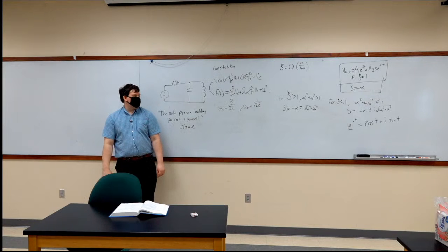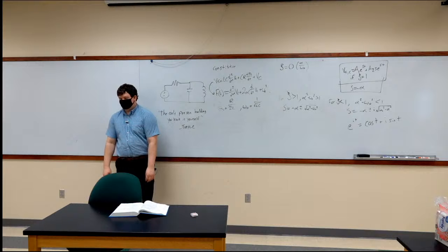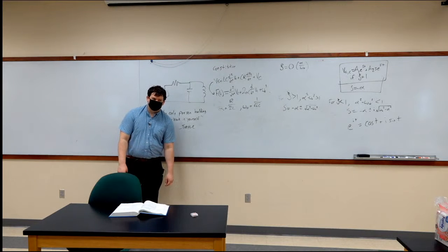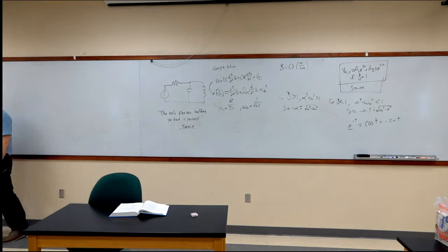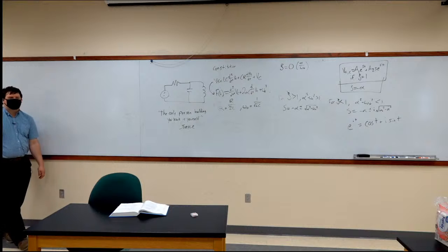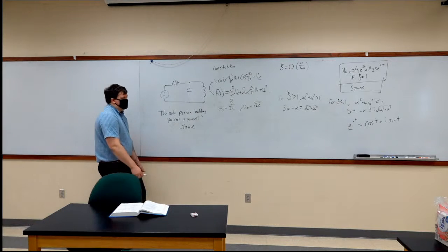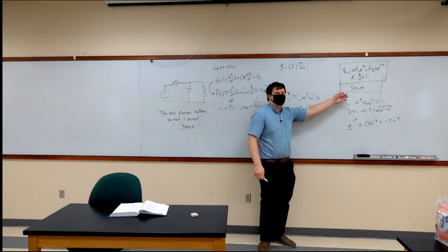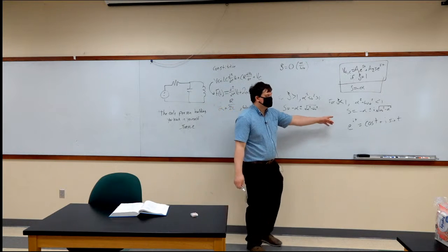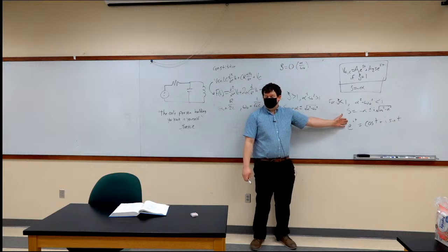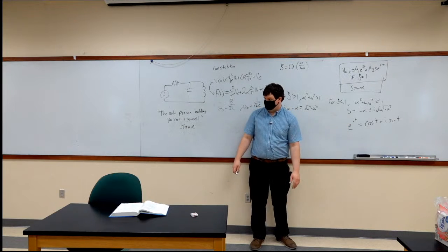Okay? If we want to talk about how to make S the smallest, remember S has to do with your time constant. If you reduce the value of S here, you change the value of tau to make it the most optimized value. Here, the most optimized value occurs right here. This system reaches steady state the fastest. It's called a critically damped system. Okay, here, this system reaches steady state faster than it should, and then experiences what's called an overshoot.